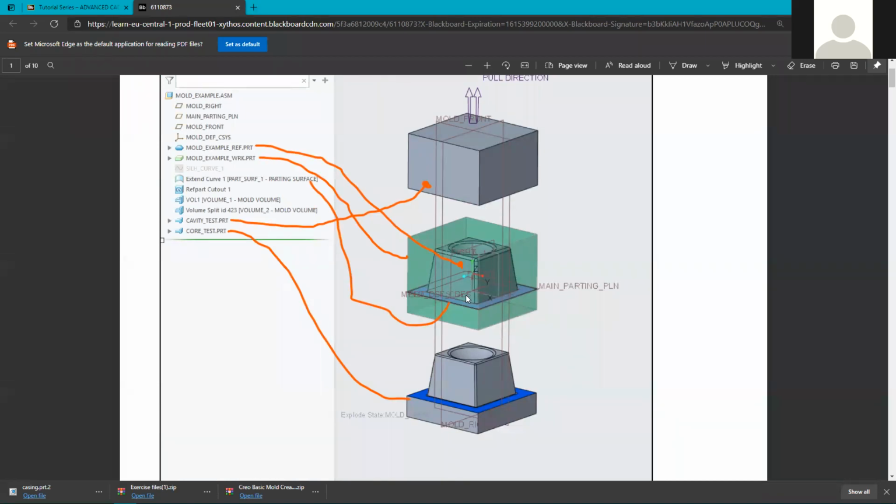So that split in the mold will have to be defined somehow during this process. The silhouette curve is the first step to defining this split surface. So this little blue skirt surface which gets created is generated by first tracing what's known as a silhouette curve around the widest part of our button model in this case. So that's a silhouette curve. It represents the widest part of your model, essentially.